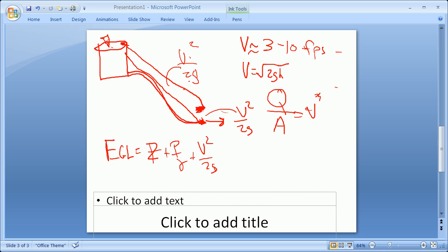You draft up the free water surface here. You draft up the discharge. You lay in one velocity head above it, and you draft a straight line from the free water surface down through that energy grade line of one velocity head over the discharge. You then offset that line all the way through that discharge, and this is what is called a piezometric level. This is the hydraulic grade line.